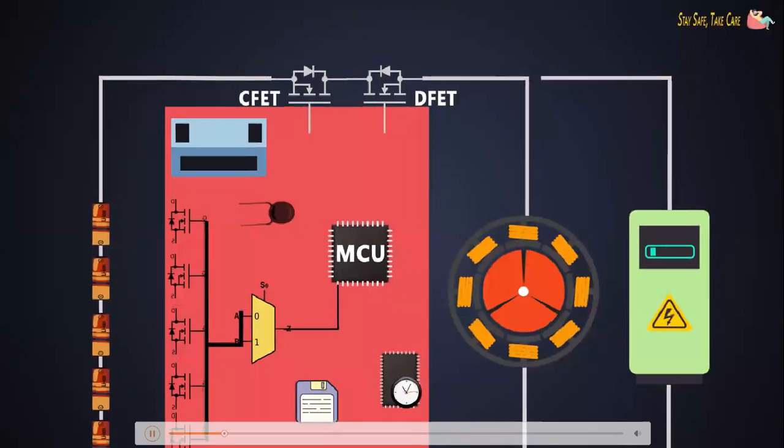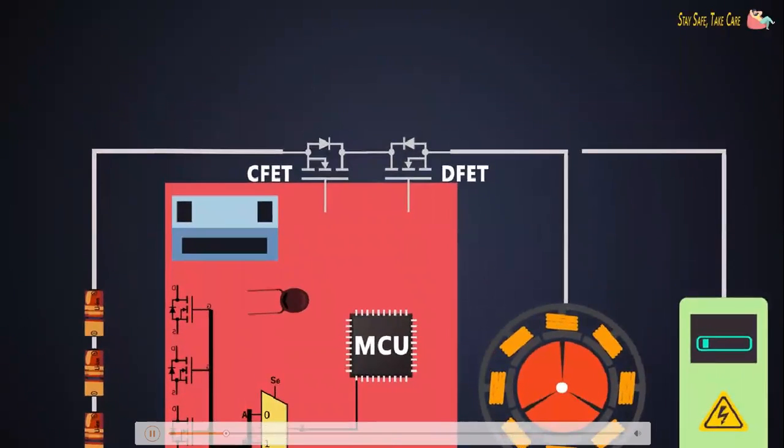These FETs can be configured as a single connection to the charger and load, in our case the motor controller, and generally the first configuration is used for charging, where just one bus controls. Initially both MOSFETs are turned off.